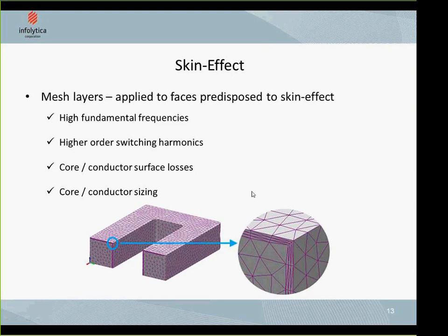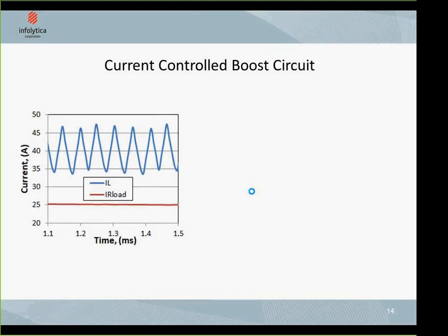So now, if I wanted to implement controlled circuits, let's assume I want to control my inductor energy, or the energy stored in an inductor. I can do that by controlling the current in the inductor. So in this case, I will take a value and say I want to control it at about 40 amps, and I want my hysteresis band to be about 10 amps.